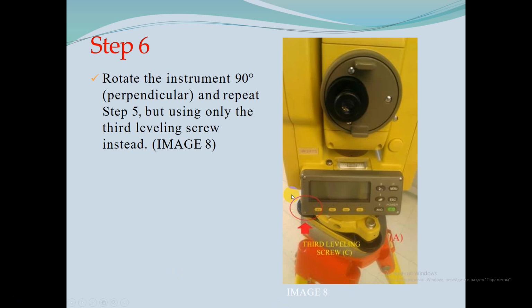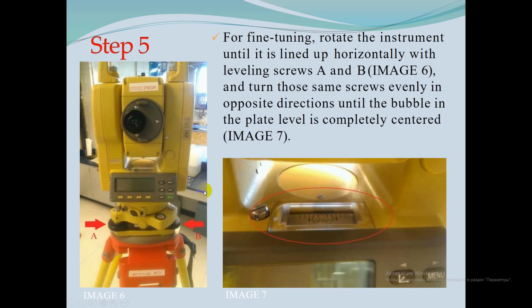You must rotate until the bubble in the plate level is completely centered.